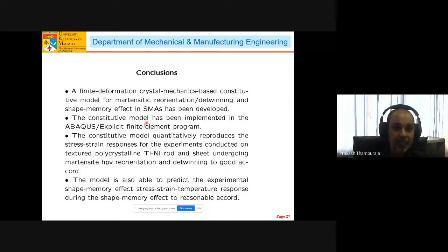So what we have achieved in this project is that we've developed a microstructure informed mathematical model, or a crystal plasticity based constitutive theory, which takes into account the large deformation effect due to twinning and reorientation in this material. Because if we're looking at the samples in a single crystal state, the twinning shears can go up to about 28%. And in fact, new shape memory alloys have also been discovered that can go larger.